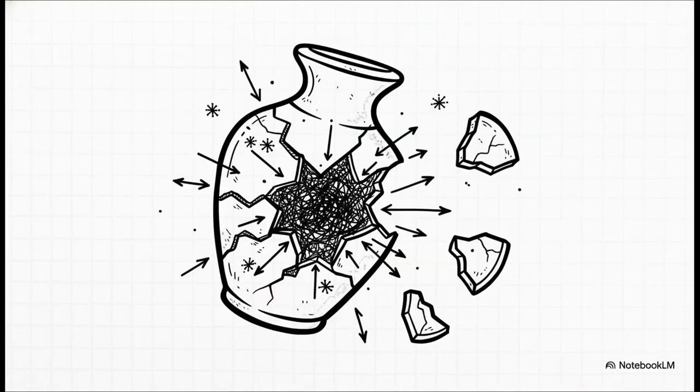Now, for ductile materials like metals, they might just bend or warp under that stress. But for non-ductile, brittle materials like ceramics, rapid cooling is a total nightmare. The exterior shrinks super fast while the hot interior resists. This creates enormous tensile stresses on the surface, literally pulling the material apart. Since ceramics can't stretch or deform to alleviate that tension, cracks propagate instantly and the whole piece shatters. This is the phenomenon known as thermal shock.